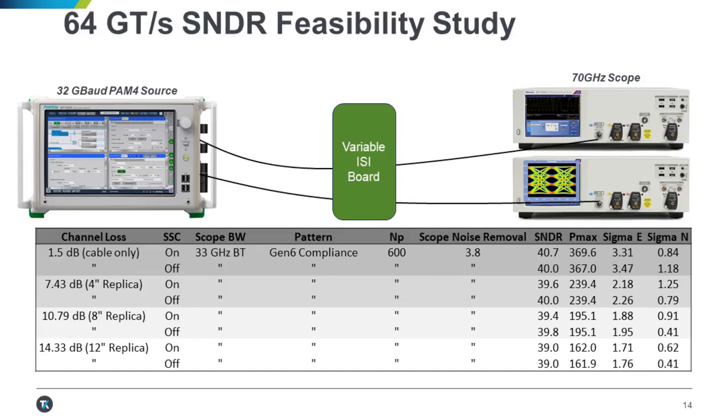Also being able to do this test with a new pattern, which creates challenges for clock recovery because you have these long run lengths, and compound that with the additional challenge of SSC, the spread spectrum clocking. Right. So when you put all those together, you've got a worst case that is challenging and in ways that you haven't seen for that IEEE measurement. So wanted to de-risk this.